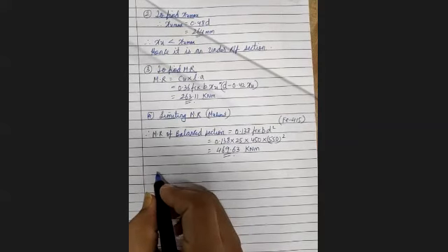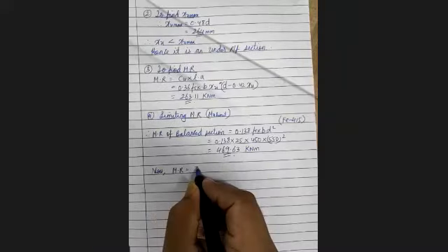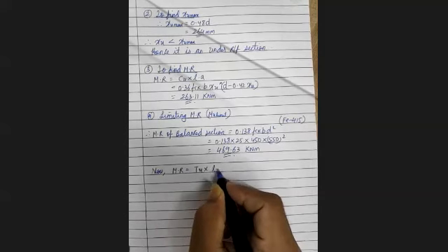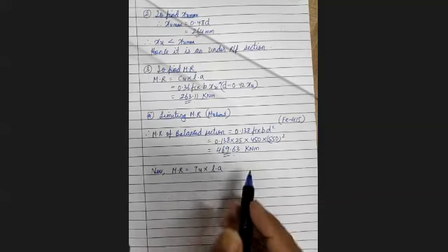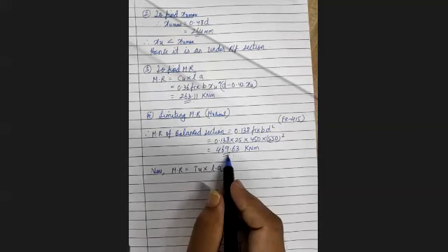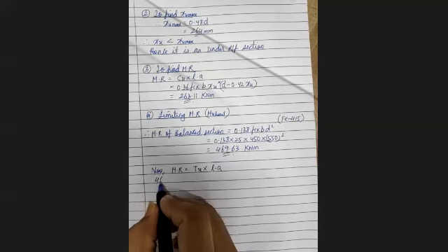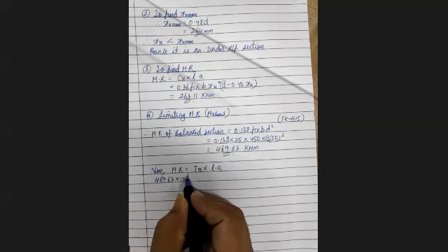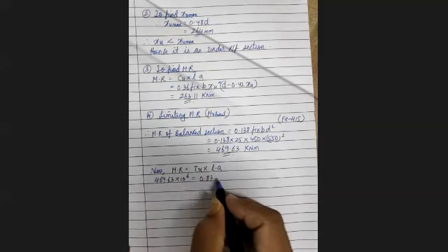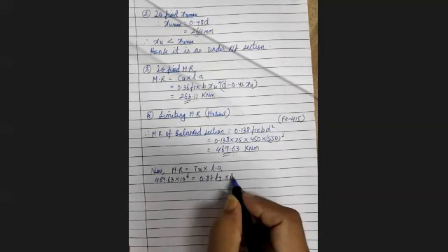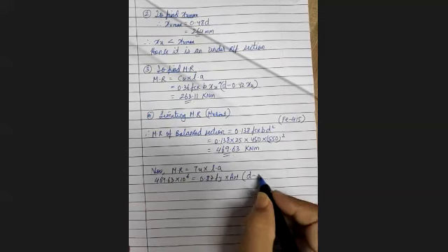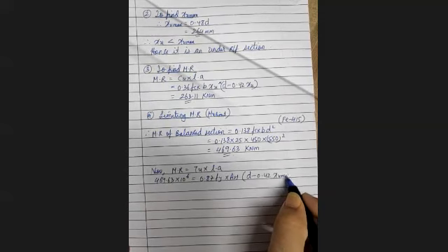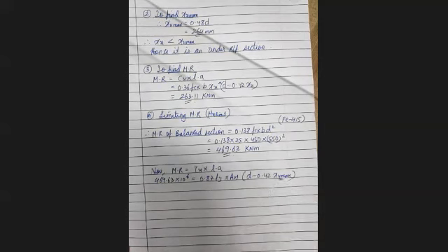Okay, for tension reinforcement, MR equal to T into lever arm. Perfect. So now, we know that MR is equal to Pu into lever arm. So MR we already have. For balanced MR steel, we will use the balanced MR value. So this is 469.63. This is 0.87 fy into Ast into d minus 0.42 Xu max. Okay, since it is balanced, it is Xu max.